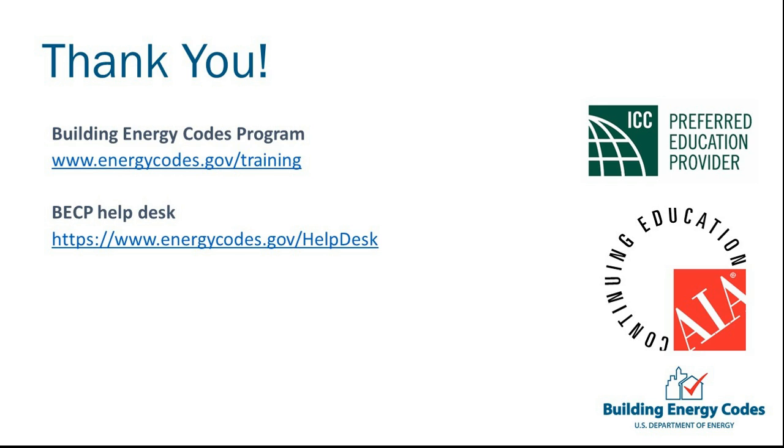Yeah, so first off, IECC and ASHRAE 90.1 follow different processes. The commercial IECC does reference ASHRAE 90.1, but in general, they follow different processes. And yeah, there was a proposal for buildings to be EV ready. They didn't have to put in the EV charging systems for cars, but they had to have the wiring and the ducting. It had to be ready so that a future owner could install that. That was taken out, so it will not be in the IECC.